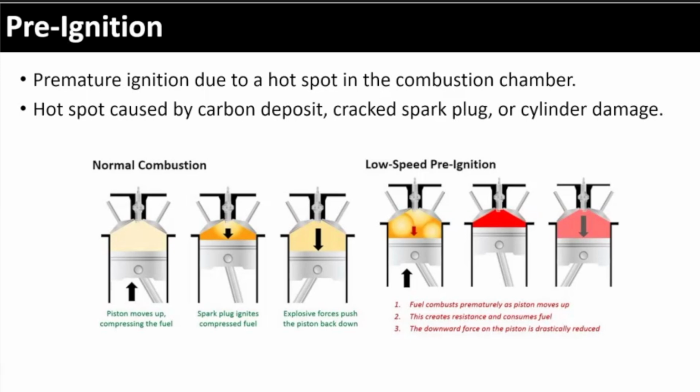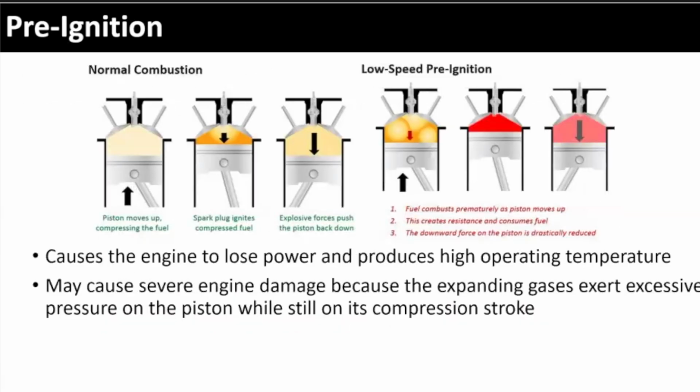It can't go down yet, it's got to finish that cycle, and the shaft is pushing it. So pre-ignition puts unnecessary force and pressure on that piston and causes problems with the pistons, the cylinder, the valves, or the gaskets. Any part of that engine could be at risk as a result of pre-ignition. This slide is saying the same thing. Definitely not something you want to get into.